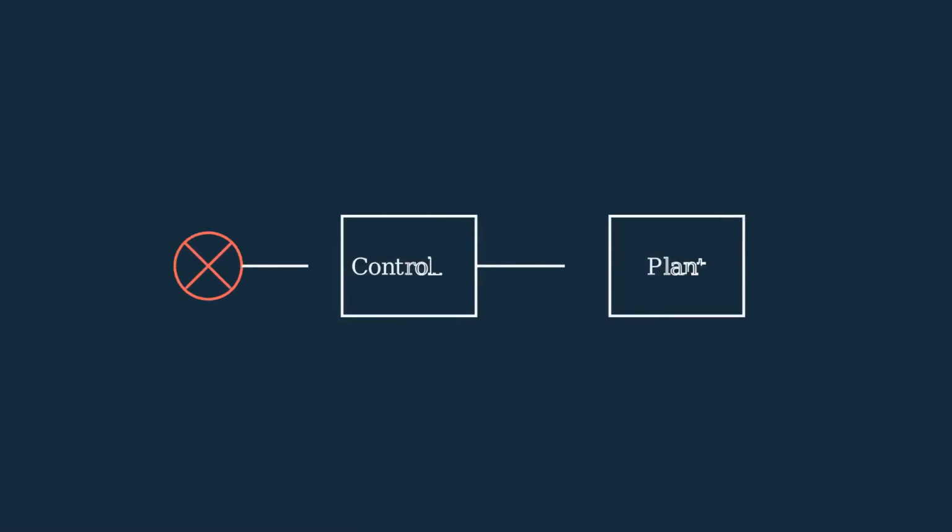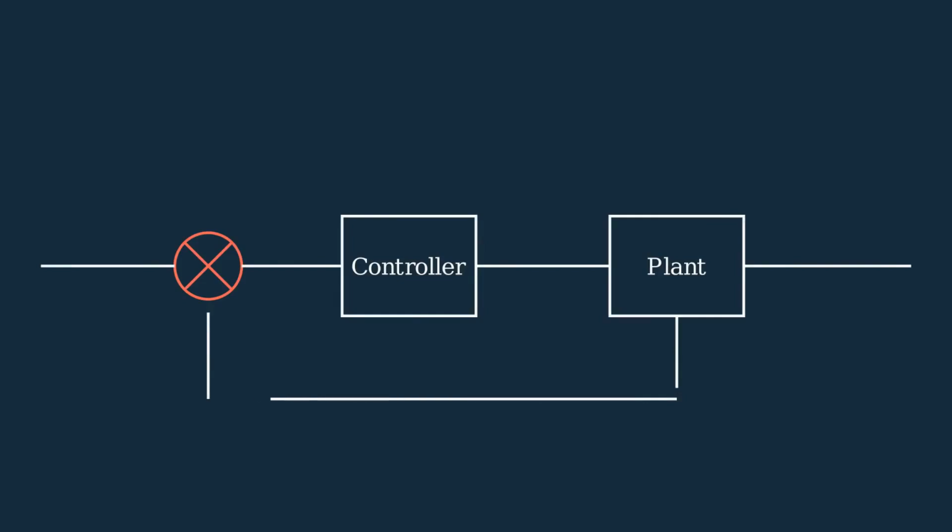The purpose of a PID controller, like every other controller, is to control a plant or system to a desired set point set by an operator. The architecture described takes the form of a closed-loop controller as seen from the very simple block diagram. In this case, R represents the desired set point, E is the error between the set point and the current measurement, U is the control input, and C is the system output.